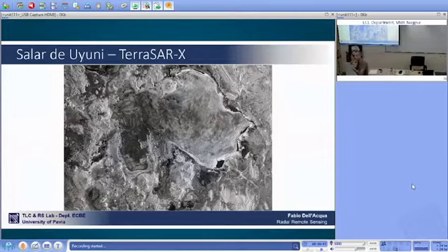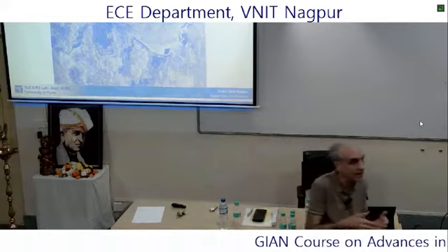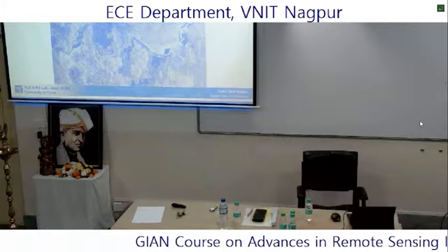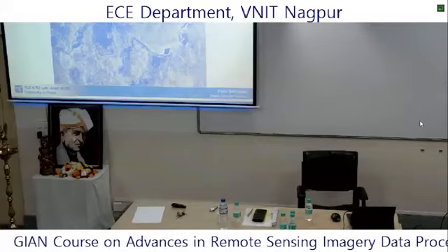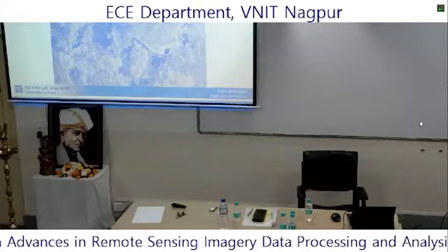With radar, the story is different because the wavelength is much longer. Centimeters, even decimeters, in some cases even meters. When you have wavelengths this long, they can penetrate into objects. So don't assume that when you see a reflected field, it was reflected by the surface alone. No, not necessarily. In many cases it is, but in many other cases, the wave will penetrate into the surface and it will generate backscatter even from the body of the object.